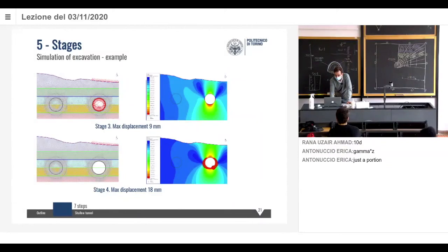Of course, this depends on the stress state, on K0, on material properties. And with this red area that you see around the tunnel, we are seeing the plastic zones around the tunnel. This is obviously influenced by the stages that we have selected. So 80%, 20%, that was a big decision we had to take when we did this design. It's deciding the relaxation.